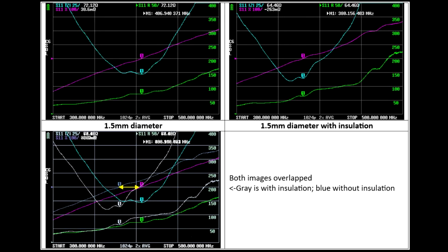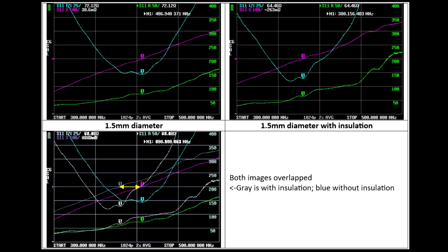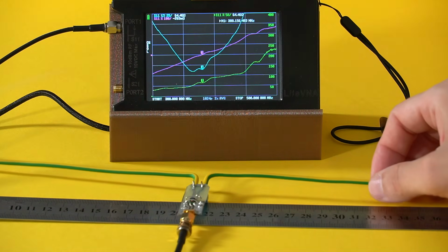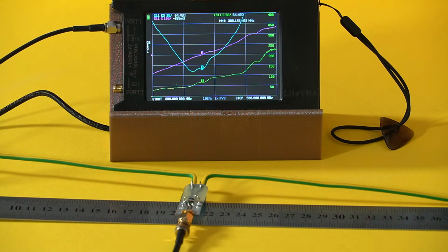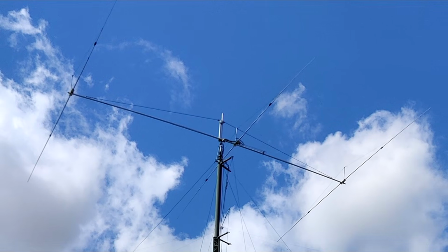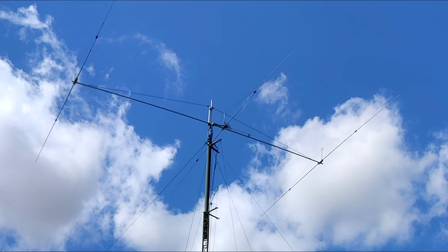So this is an important thing to keep in mind with practical antennas. The exact environment around them will have an impact on their behavior. Now, making thicker and thicker dipoles to expand the bandwidth is not always practical. A thicker and thicker wire or pipe will be heavier to the point where the antenna cannot even support itself.